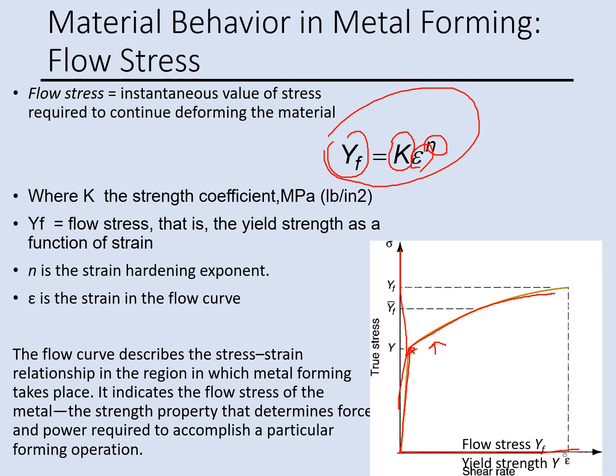Dislocations, as we talked about before in the material in alloys, appear when you apply load and have plastic deformation. This defect, dislocation, is a defect. Dislocations will tangle with each other, and it makes the plastic deformation harder and stronger.